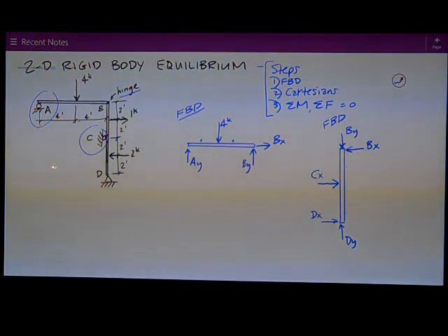I've also got my applied external forces of 1 kip, 2 feet down, 2 feet to C, 2 feet down further. I have a 2 kip load, and that leaves me 2 feet to the bottom, to D. So there's a good free body diagram. The key thing is to break it up into 2 free body diagrams and reverse those forces at the hinge at B.